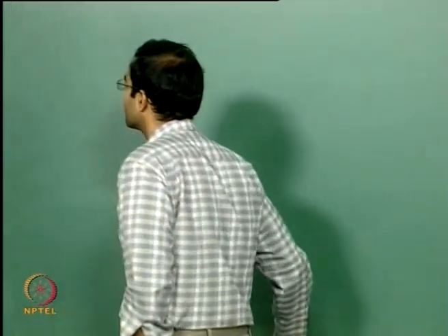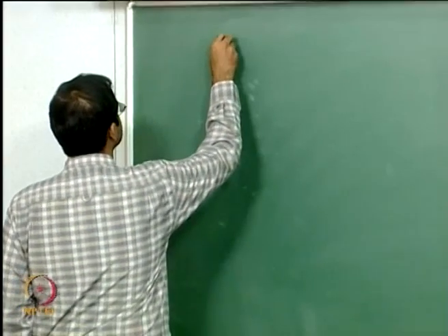One is casting that into the form of stream function vorticity equations, which we have derived, and if you apply that to a typical problem, which is an external boundary layer flow, we can use some scaling arguments, do some order of magnitude analysis, and then conclusively show that certain terms can be dropped out, provided that you are dealing with sufficiently high Reynolds number flows. Under that approximation we have derived what are called the boundary layer equations. So let us summarize the boundary layer equations which we derived in the last class.